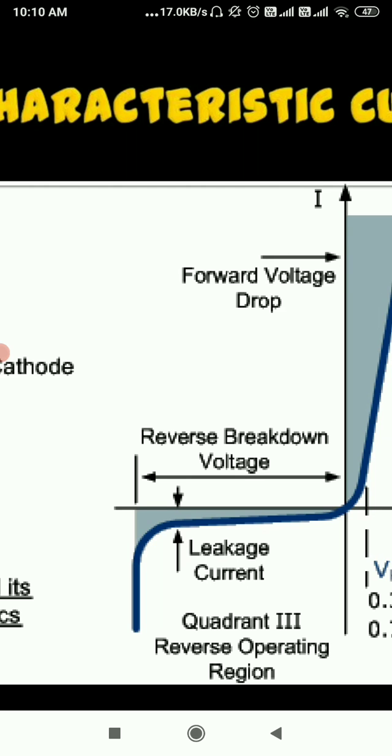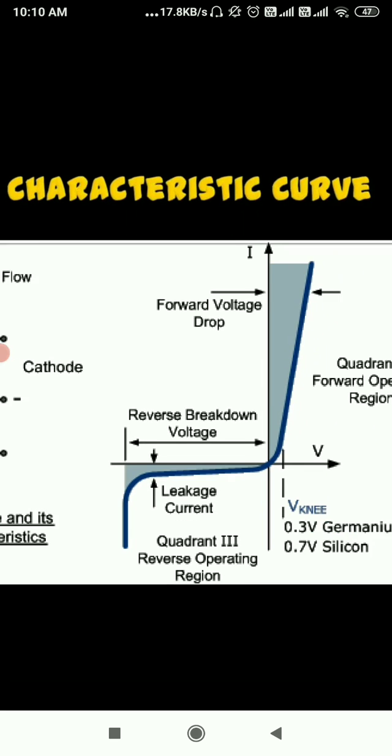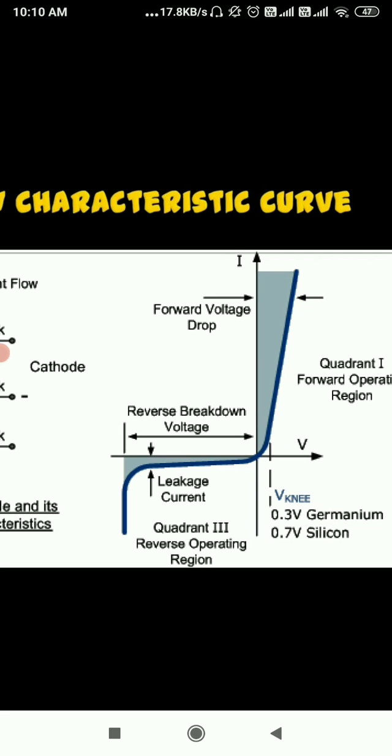And if you are supposed to use a diode for forward characteristics, at that time you can use only a PN junction diode. We cannot use a Zener diode, because the Zener diode gives its application as a voltage regulator when it is in reverse bias.